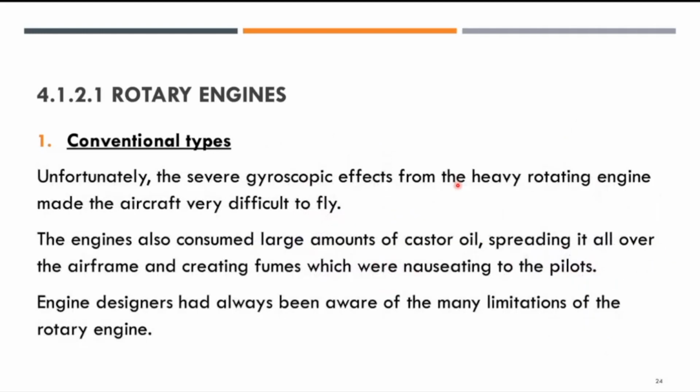Unfortunately, the severe gyroscopic effect from the heavy rotating engine made the aircraft very difficult to fly. You can imagine you have to make sure it stays under control, and it has a lot of vibration. The engine consumed large amounts of castor oil, which spread all over the airframe, creating fumes that would normally make the pilot dizzy. The engine designers had always been aware of the many limitations of this type of rotary engine.